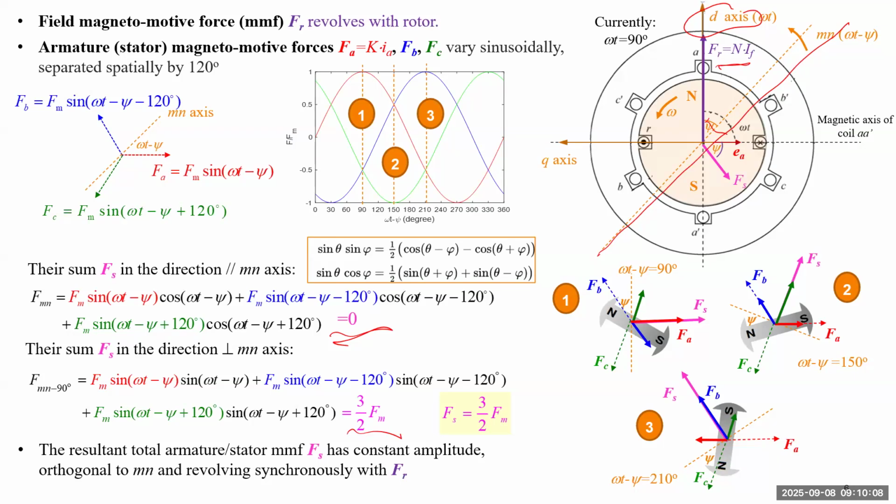So finally, we prove the stator winding magnetomotive force will always be perpendicular to that axis, determined based on the power factor of the generator, and also have constant magnitude. So they can generate the total magnetomotive force if we use this parallelogram.